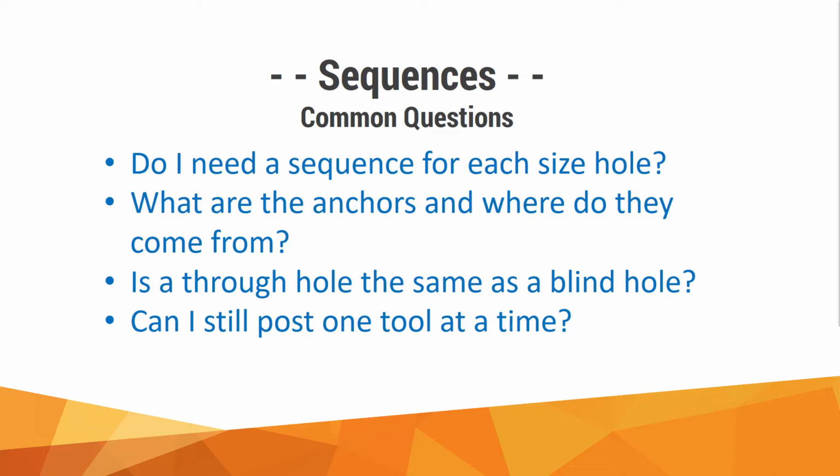Is a through hole the same as a blind hole? No, that's one common one we hear quite a bit at support. A blind hole is going to have different anchors than a through hole on a block. It would have fewer anchors, which makes it different geometry. So it's not going to fit the same. It's something to keep in mind as you develop these processes.